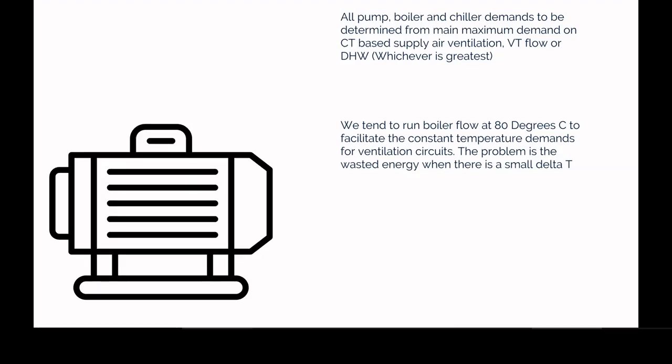So if the valves are at 100%, as in requiring heat, therefore we will run the pump at 100%, because, providing all your loops are tuned, that's the right thing to do. But I, and others like me, would counter that, because for me the most important thing is trying to reduce the work done by the boilers and the chillers if they're not required. So how do we do that?